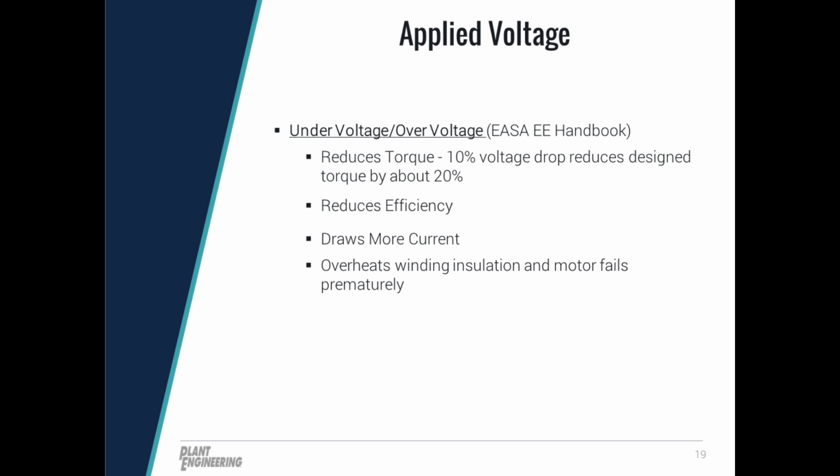One other thing I wanted to point out is that most low voltage motors would typically be rated at 460 volts, but grid voltage coming from your electric utility might typically be 480 volts. So the 460 volt rating takes into account voltage drop in the distribution lines coming from the nearest substation or nearest distribution transformer. We have completed some tests at our lab here in Raleigh that show a slight increase in supply voltage above the rated voltage will actually lead to increased motor efficiency. That test showed that multiple 460 volt rated machines operated most efficiently at approximately 1.05 per unit voltage, roughly 480 to 485 volts.